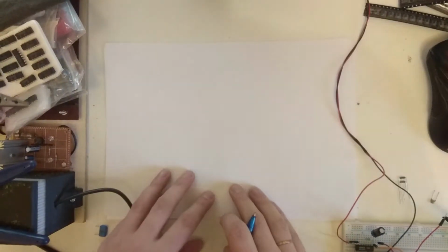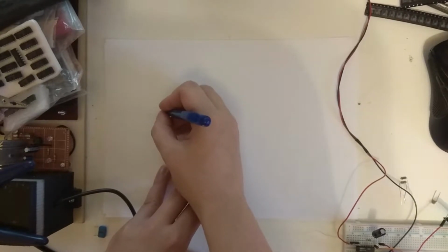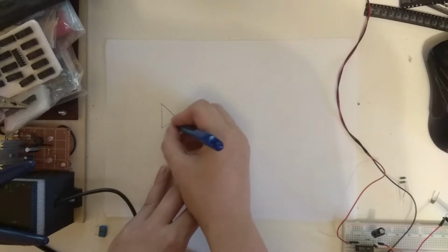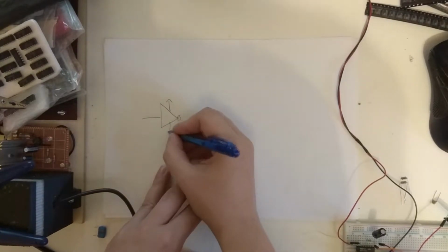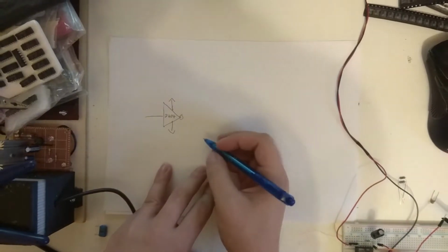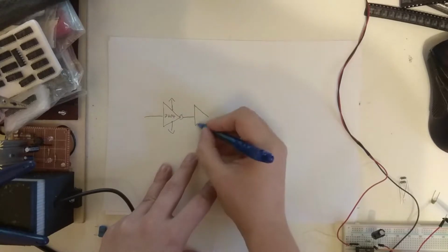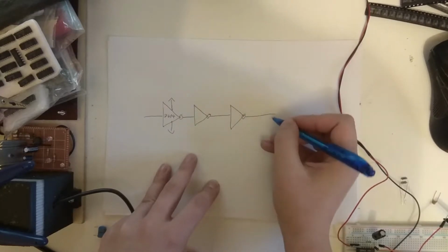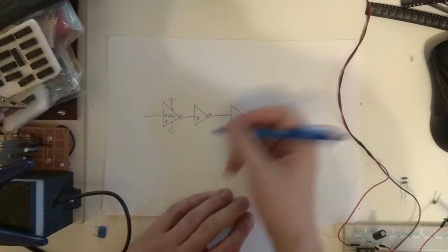The first thing I'll design for this card is the clock generation circuit, and we're going to use a very, very classic circuit, and that is basically based on an inverter chip, 7404, and the inverters are basically just coupled end to end. 3 of them go like this. This is A, B, and C.